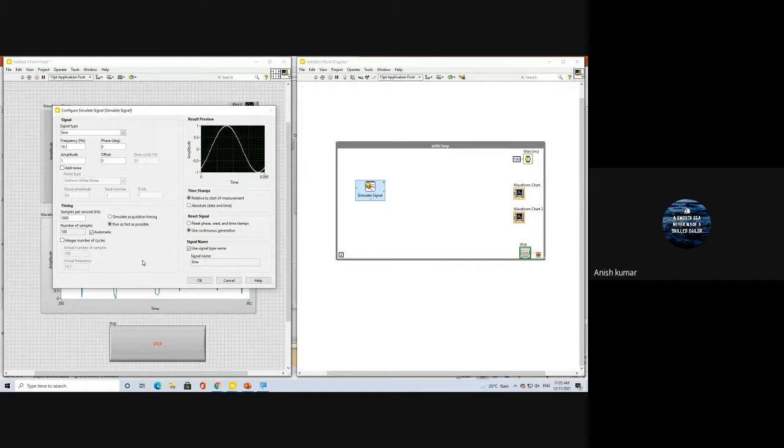As per Nyquist theorem, it must be greater than or equal to at least two times the message frequency, is a general statement, but it must be at least 10 to 50 times to reconstruct the original signal, right? So that clarity will be more and the resolution will be more. It's more about the resolution, the clarity and the accuracy, right?